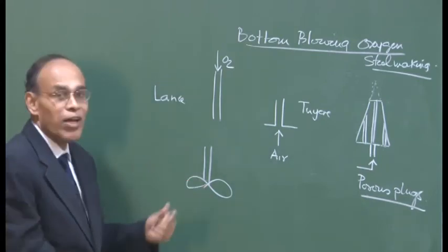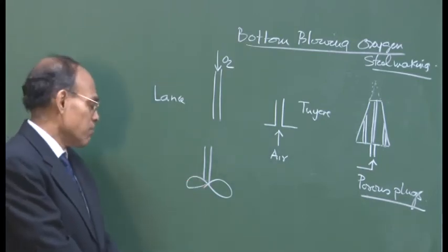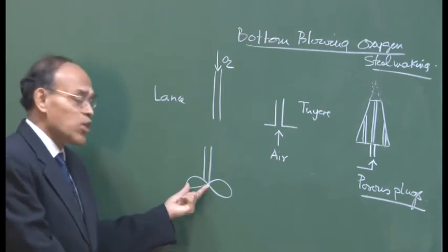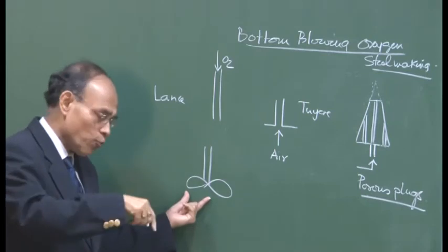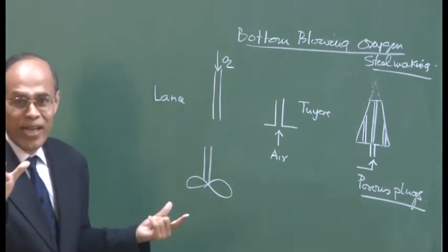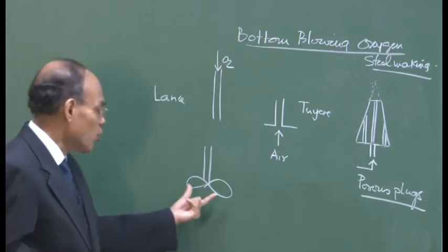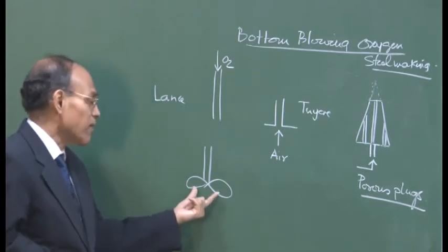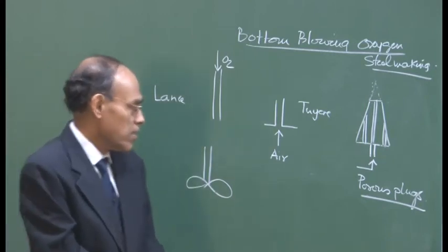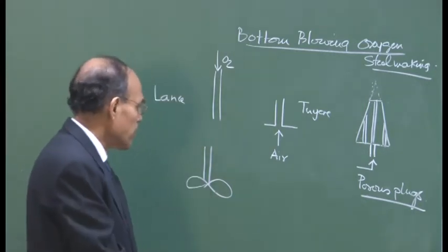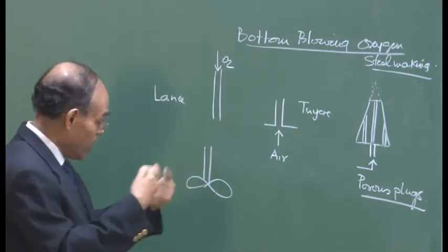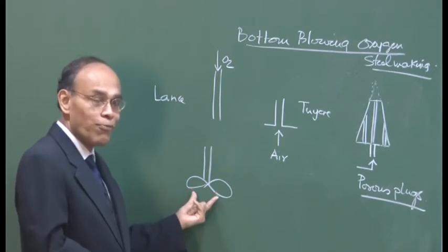Then the wear and tear of the impeller could jeopardize the quality of steel. An impeller also produces very intense stirring. If you rotate an impeller at the same specific energy input rate, it can be shown that impeller stirring is going to be more intense than gas stirring, but gas stirring has its own advantages, particularly towards the later part.